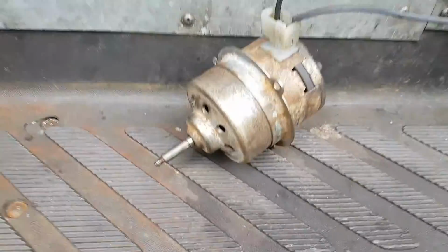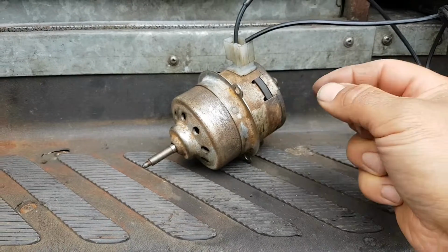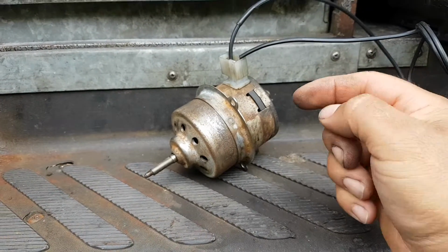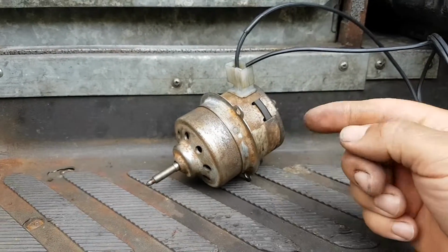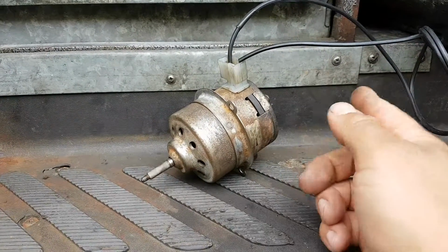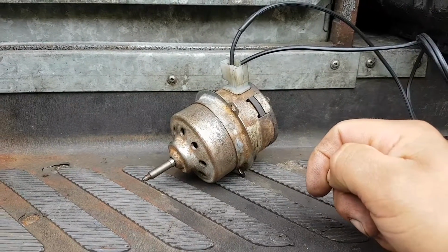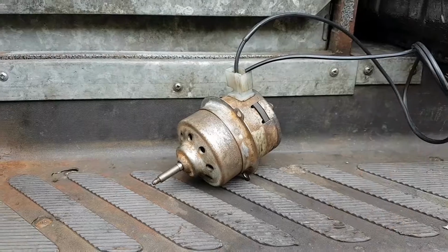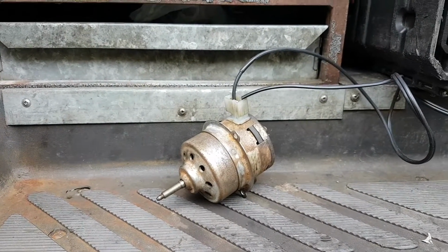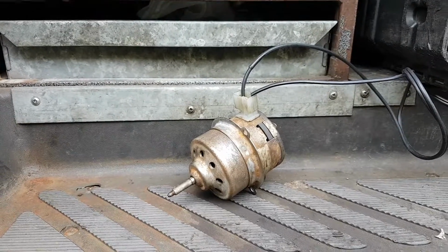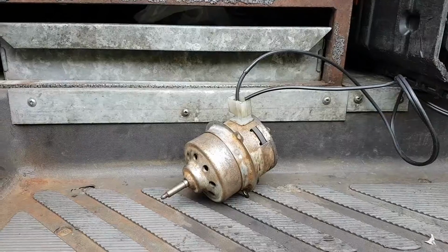Okay. So the springs that push the brushes, they're completely rotten. So I had to undo a few winds of the spring and then just reform the end plate of the spring that pushes the brush. But yeah, it's running absolutely perfect. So let's run another 20 minutes, put everything back on, clean everything, put it back in place, and we should have the problem fixed. Let's see.